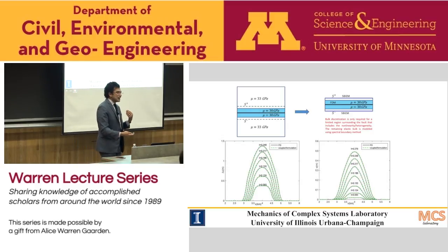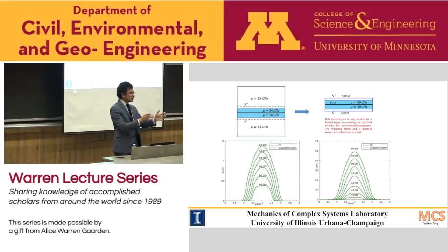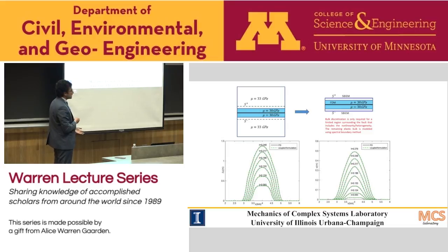So it's similar to the domain decomposition approach that we use in fluid structure interaction, but here we are using it for elastodynamics. And we tested the problem. We thought that this could induce artificial reflection because we are taking it very close to the fault. So classically the absorbing boundary condition will be far away in order to avoid any artificial reflection. But because the spectral boundary equation is exact, we don't have any artificial reflection.